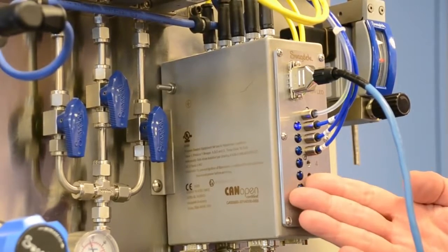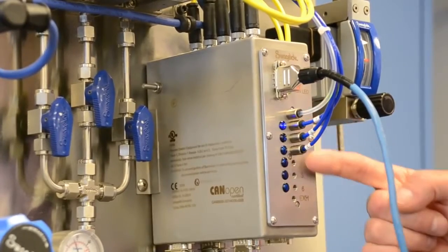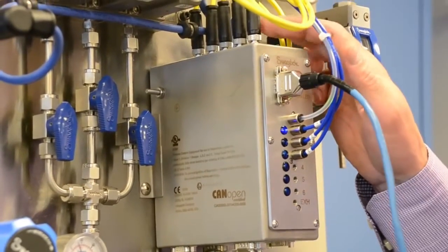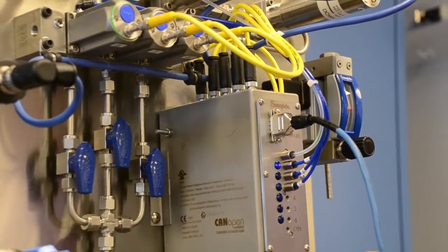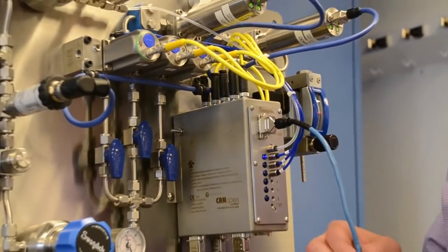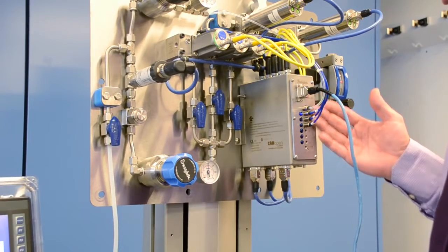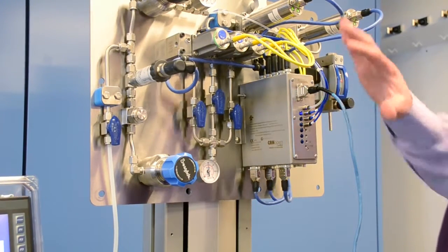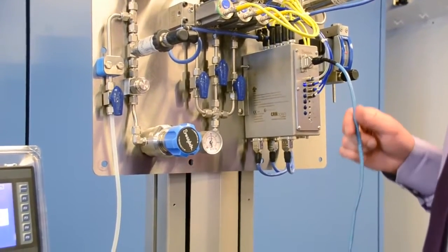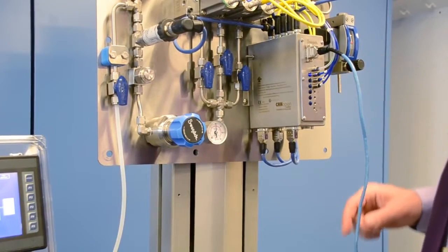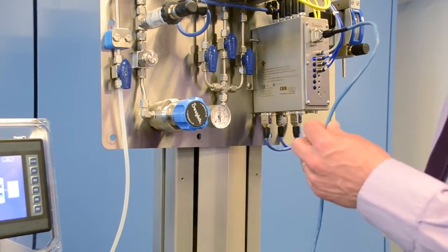By downloading a script to the ICM, you can control the sequence of valve actuations, and you can monitor sensors so that you can determine if an alarm condition is present and communicate that information across the network interface. All of the data that the Intelligent Control Module collects from a sample system is made available on a network interface. This network interface is intrinsically safe, this being the only electrical connection to the fluid system.